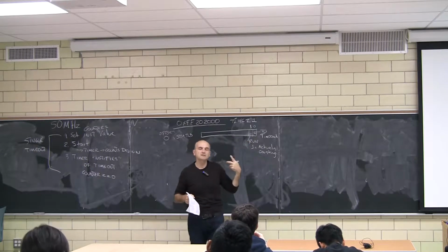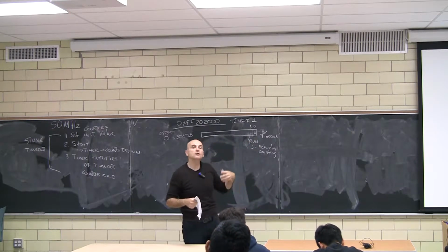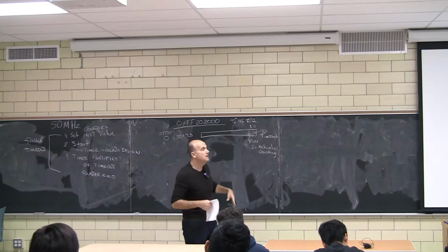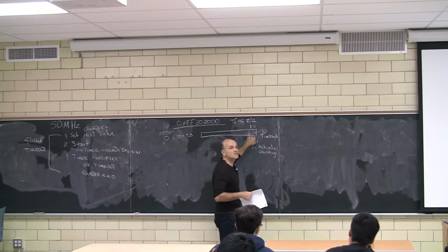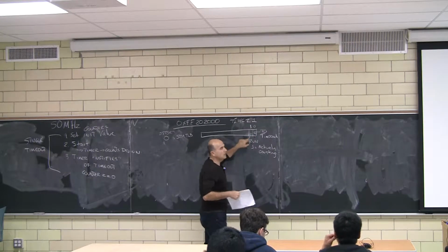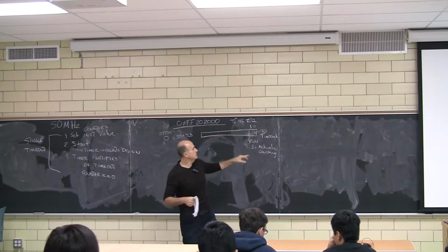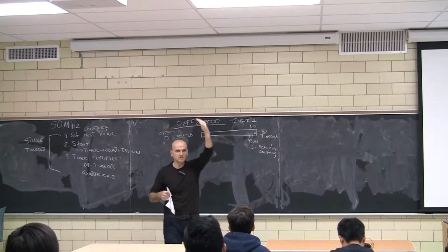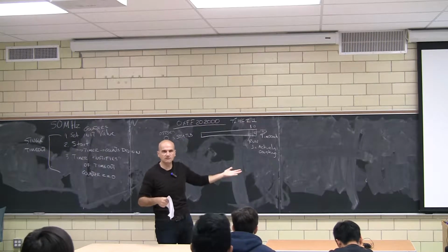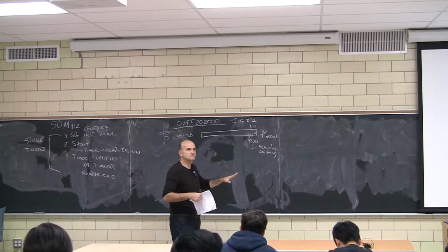You can either have the timer give you an interrupt, or you can go and look at it through polling. We're going to do polling today. If you go through polling, you have to go and explicitly clear that. So you have to write a 0 there. Now, when the timer times out, run is either going to stay at 1 if it's in continuous mode, because it's going to keep counting again from the beginning, or it's going to reset itself. Okay. Any questions about this too?